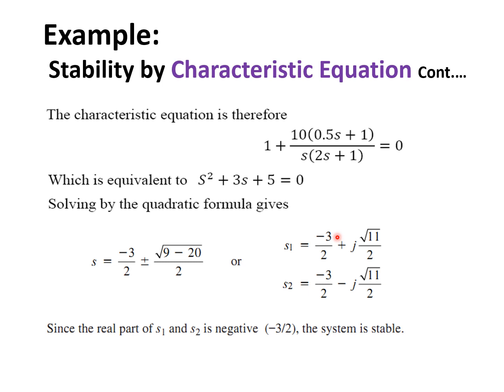The equation 1 plus G defines the stability of the system, and the location of the roots will tell us the stability. Qualitatively it also gives us the shape of the response: how it responds on the left, on the conjugate roots, on the right, and on the real axis. You can see the qualitative behavior of the system as well as the stability of the system. So much information is given by the characteristic equation. So this is the first way of getting the roots of the equation.